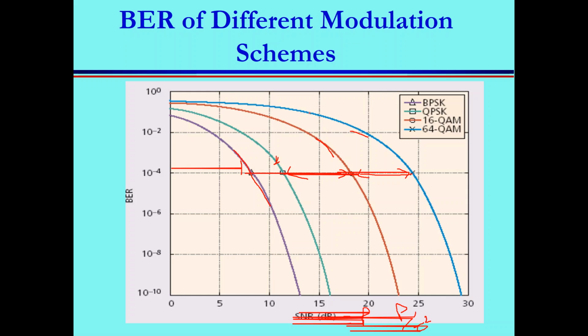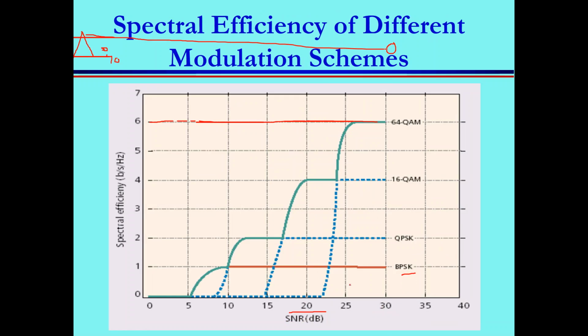Can he use 64-QAM when he's on the edge, when he's very far from the tower? He cannot. Can he use this? He cannot, because if he chooses to use this, he will not be able to decode the data of the video. Yes? So what he has to use is QPSK. Similarly, this is just how to adapt the modulation with respect to the signal to noise ratio, which represents the average distance.